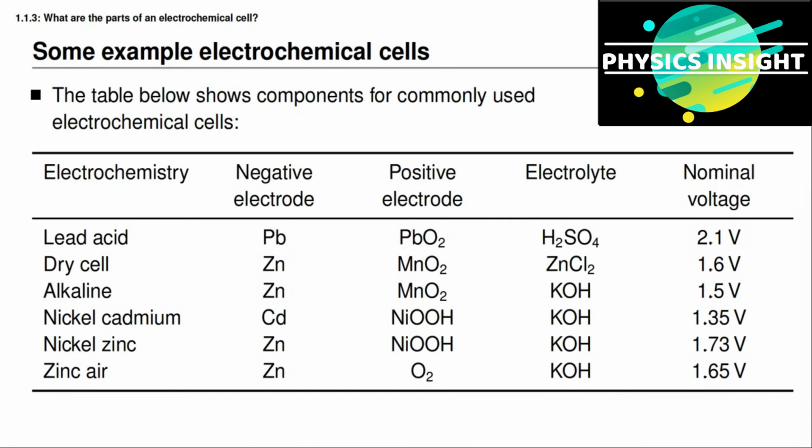It's a zinc-air battery. In a zinc-air battery, the negative electrode is made from zinc, and the positive electrode is oxygen, which is typically scavenged or harvested from air. This can reduce the weight of the battery because we don't have to consider the positive electrode as part of the weight. It does turn out that we require some structure to act as a current collector for connecting, if you will, to the air. But the zinc-air battery can have quite high energy storage for a particular volume or for a particular weight, and they make very interesting rechargeable batteries because of that.